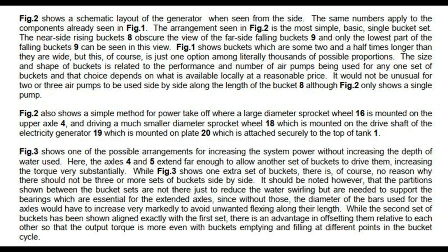Fig 3 shows one of the possible arrangements for increasing the system power without increasing the depth of water used. Here, the axles 4 and 5 extend far enough to allow another set of buckets to drive them, increasing the torque very substantially. While Fig 3 shows one extra set of buckets, there is, of course, no reason why there should not be 3 or more sets of buckets side by side.